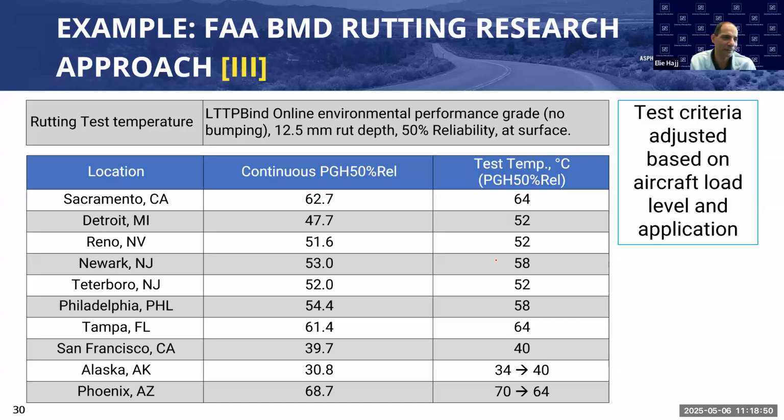If you think about it, just to reiterate this, the P401 mix is the P401 mix, regardless of where it's going to go, or the P403. Whereas this is not the case in the state highways. Every agency has its own specification and so forth. So the way FAA is approaching this is that we want the test to be representative of the geographical location where that mix is going to go, and the traffic that it's going to be subjected to. And that's how the testing conditions, the aging conditions, and the test criteria are being recommended for the FAA BMD testing.